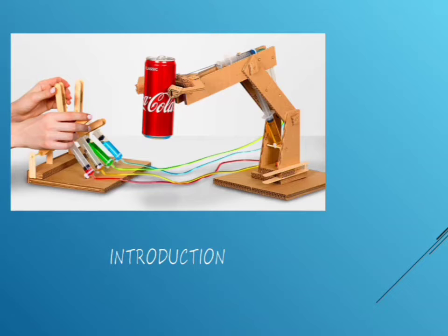A hydraulic drive system is a drive or transmission system that uses pressurized hydraulic fluid to power hydraulic machinery. The term hydrostatic refers to the transfer of energy from flow and pressure, not from the kinetic energy of the flow. A hydraulic drive system consists of three parts. The generator, like a hydraulic pump, driven by an electric motor or a combustion engine, with filter, piping and so on.